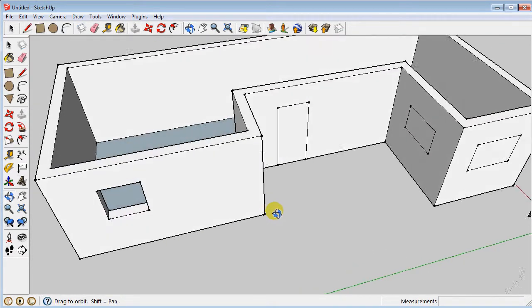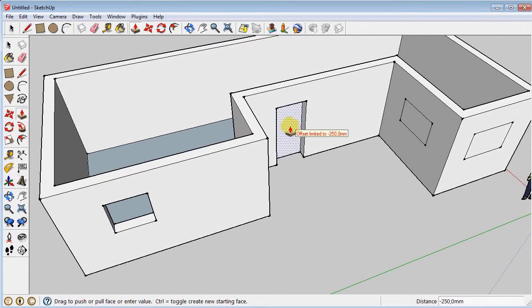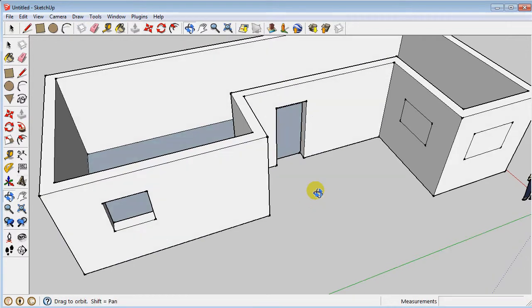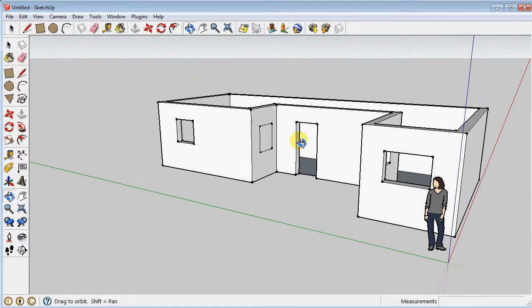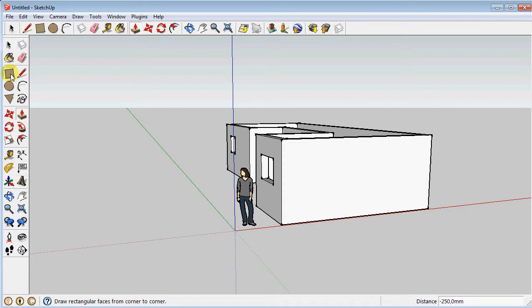space here. And when you start doing it, if you find a text on surface, then you know that amount of push-pull is good. Now they're on face. But if you find it difficult to find it, then you can move mouse also here on edge, and it works fine there too. So sometimes it's easier to just take a point on edge of opposite side surface, and like this you can make windows and doors.